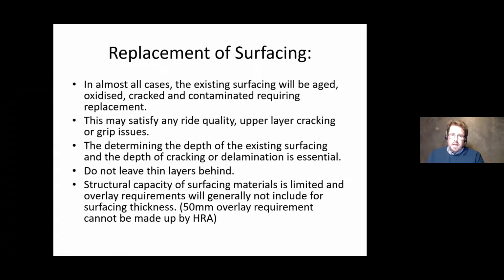So if you're adding new material on top of that, you're just creating a weak spot in the center of your pavement. You're better off just removing your 45 mil, 50 mil of surfacing, but be conscious that you're not leaving any thin layers behind that might become delaminated. So again, go back to your cores, go back to your GPR, figure out what your maximum depth of surfacing thickness along your design stretch is, and try and design to that.